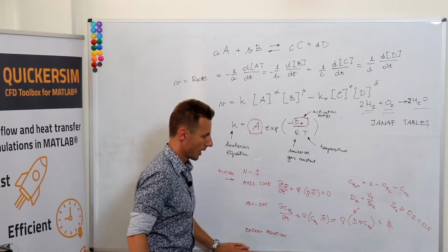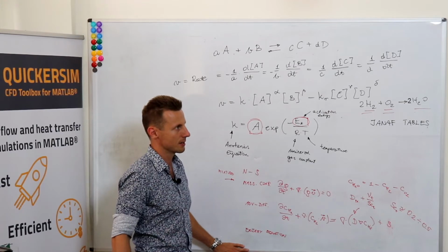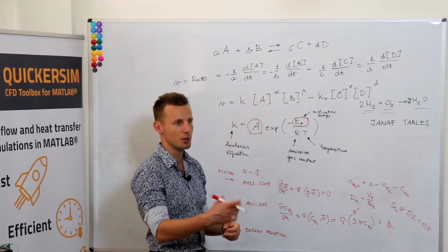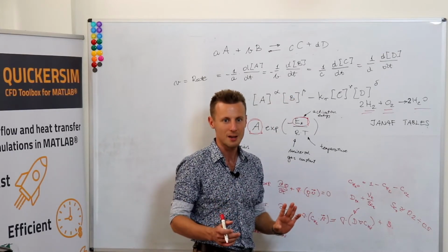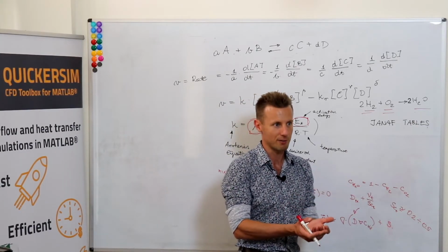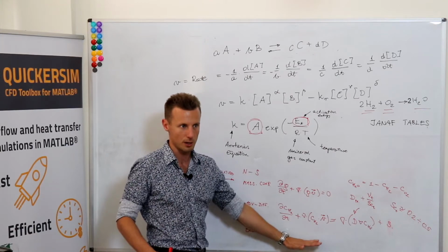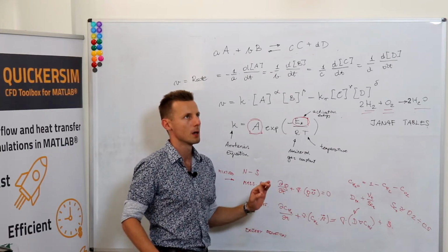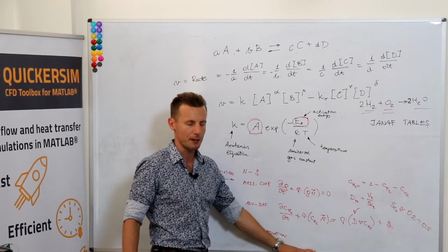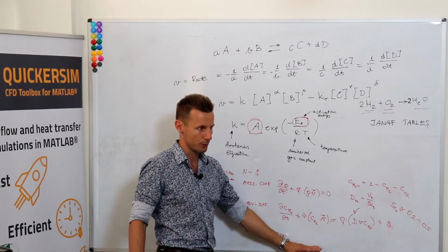To be honest, I never remember this without checking, because intuitively, once you've got chemical reactions and you know from macroscopic calculations in heat transfer, combustion, etc., you should add the calorific value of the reaction times the reaction rate to the energy equation. But as far as I remember, I think it's wrong. You don't need to add any source terms to the energy equation.